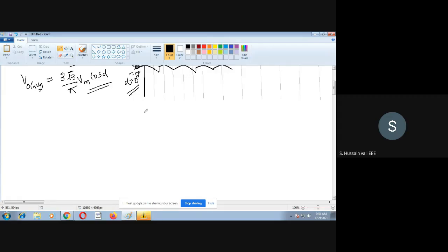But the motor does not think whether it is three-phase or single-phase. What it sees is whether it is DC or not. At the end, you will get DC for the motor, whether from a single-phase converter or a three-phase converter. The only difference is that the magnitude of DC in the three-phase case is more than in the single-phase case.